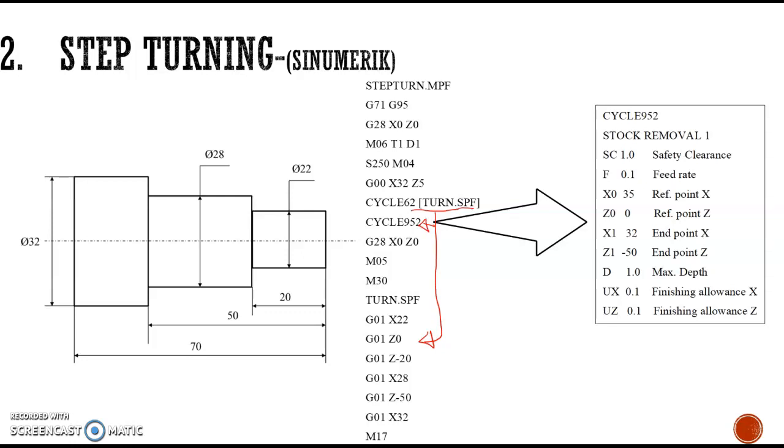After completing the entire metal removal, it will make a loop with this subprogram. So the tool will pass again and again through these points, many times, and after achieving this final shape, it will come back to the original program at this point.